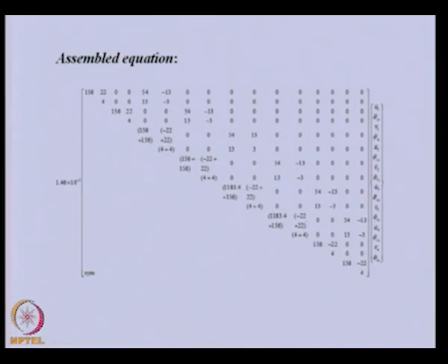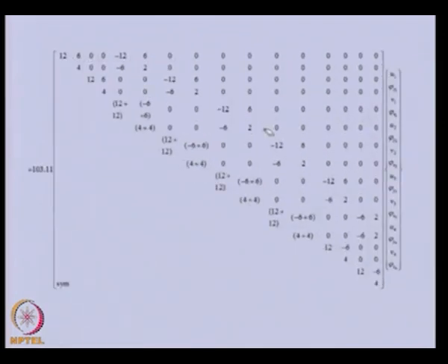This is the mass matrix. This is the stiffness matrix. Again, these sizes are very small to look into the values, but I am trying to explain the overall procedure. The size of this will be, because we now have 4 nodes, and each node is having 4 degrees of freedom, 16 into 16. And this vector is of size 16 by 1.